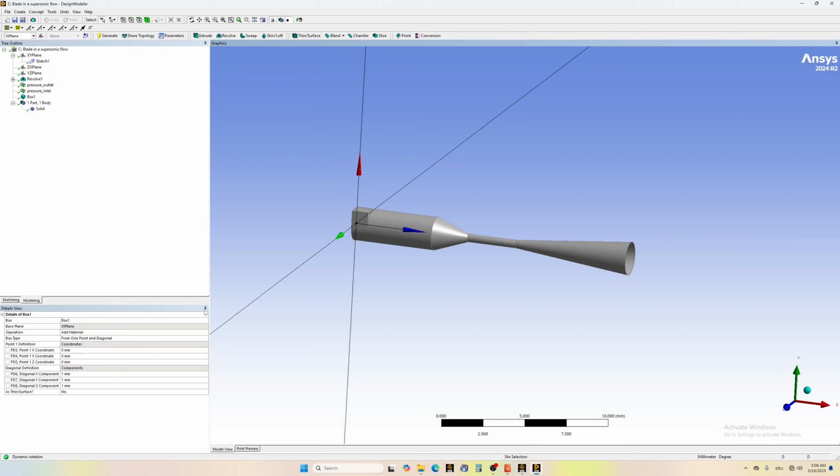Now one thing before anything else, instead of add material: if you have this checked, when you add any body or surfaces, it will be integrated in the bigger geometry. So it will be like unite two geometries, and whatever intersects is common and disappears. So only what it doesn't intersect is kept. So that's why you see here this thing. So choose frozen and generate. All right.